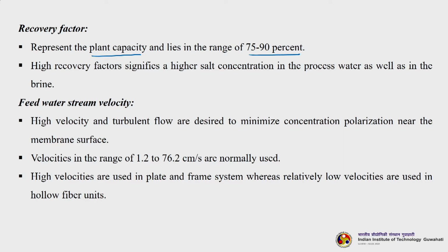Then the next parameter is feed water stream velocity. High velocity and turbulent flow are desired to minimize concentration polarization, as I just mentioned on the earlier slide. Velocities in the range of 1.2 to 76.2 centimeters per second are normally used. High velocities are used in plate and frame systems, whereas relatively low velocities are used in hollow fiber systems.